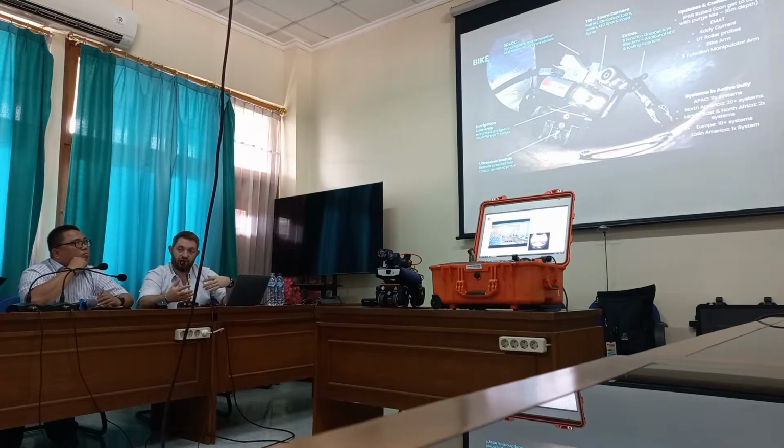We've got other roller probes. We can do EMAT with other different attachments. We can do eddy current array. So if we're looking for cracking in welds, instead of doing MPI, magnetic particle inspection, we can use eddy current array to go and create digital maps of these.